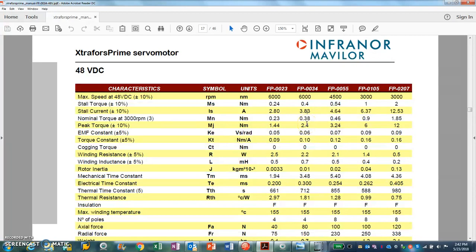It's a slotless motor with a captured magnet cage around the magnets. So yeah, I got 2.2 ohms and 0.7 millihenry here. I got 0.01 kilogram centimeter squared. Kilogram meter squared times 10 to the minus 3 is the same as kilogram centimeter squared.